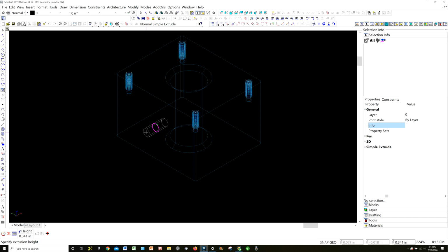And that was a double-sided extrusion. I don't want that, so I'm going to turn that tool off. I only want to come out maybe 0.25. By the way, when I'm entering numbers like this, you're hearing me on the keyboard. I'm tabbing. All numbers are entered by a tab. So my first tab, if you look in the lower left-hand corner, you can see it's highlighted blue. Right now it says my height is 0.157. Let's make it 0.25.